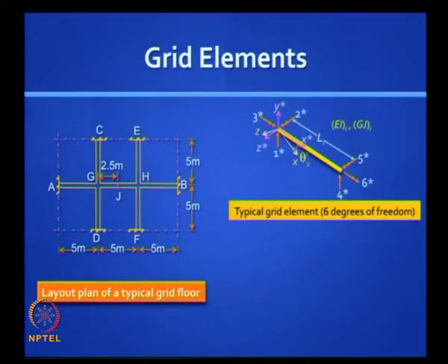So you have theta, it is actually a rotation by the angle theta in the xz horizontal plane, and we will see how to derive the displacement transformation matrix for such a situation. Please note, grids do not necessarily have to be orthogonal. We will see examples where they could have any orientation.